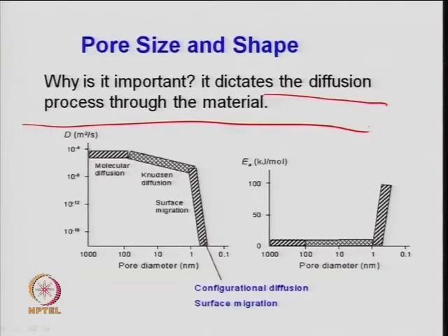So, basically in one way you are calculating the transport properties, or diffusion coefficient, for that gaseous species into the pore. But you should know a priori what your pore size is, what kind of pores are available in that solid material, and based on that only you can postulate your theory, or you can control it, suppose you want to minimize the diffusion resistance. So, accordingly you can control it. There can be parameters in terms of temperature, in terms of particle size, or in terms of development of the catalyst itself. But once the catalyst has already been developed, then it will be the secondary parameters by which you can control it to a certain level.